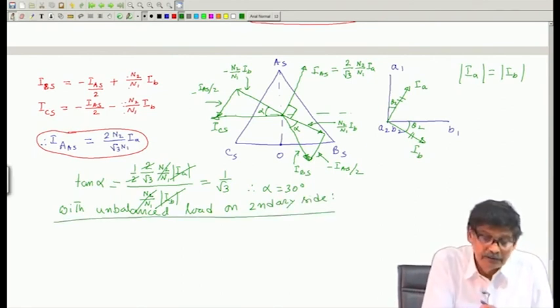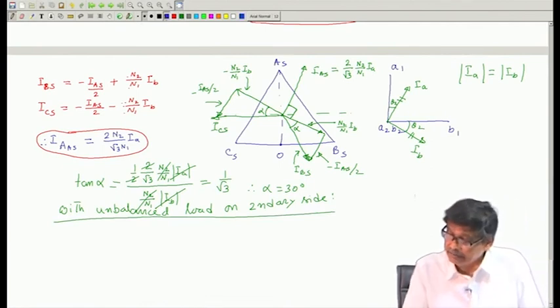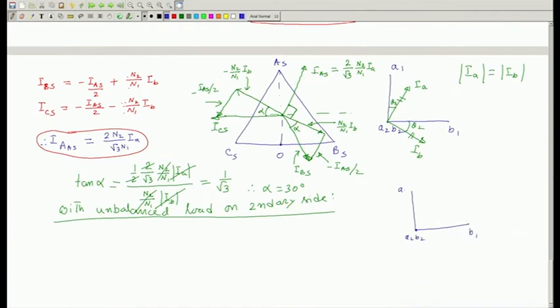no problem, because what I will do is this, the secondary voltages are balanced, A 1, A 2, B 1, and this is A 2, B 2, neutral. Suppose the load you have connected is I A, and in the other phase you have connected a load I B whose magnitudes may be different, and these two angles are not 90 degrees. So, it is a unity power factor load on the primary, but what I am telling is this equation remains intact.